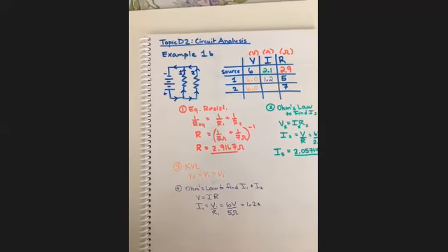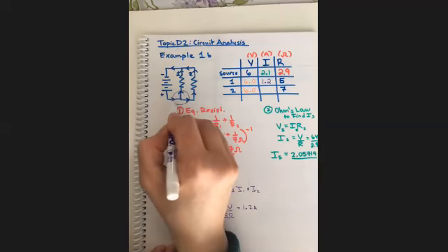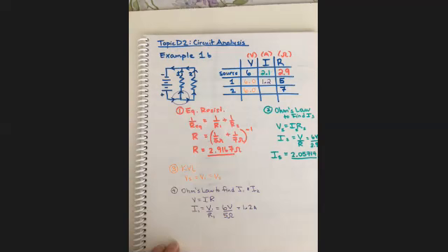Now, for the very last box, we have more than one option. We could use Ohm's law horizontally, which is probably what I'm going to do based on the way that I already set up my work for it. Or I could look at this junction right here: 2.1 amps going in, and if there's 1.2 amps going one way, I do 2.1 minus 1.2 gives us 0.9. So I know my answer here is going to be 0.9. Let me see if Ohm's law gives me the same number.